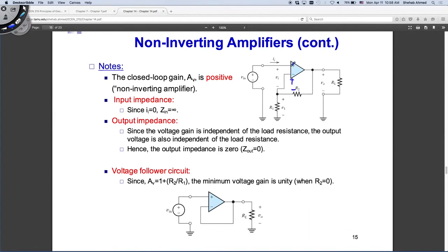Is it clear that if I don't have this, what will the output voltage be? I don't have this. What is the output voltage? This is an op-amp, no feedback. So what is the output voltage? What is the output voltage of the op-amp? The op-amp equivalent circuit looks like this, and a dependent source that has a gain of what? This is Vx. The gain here is equal to A times Vx.